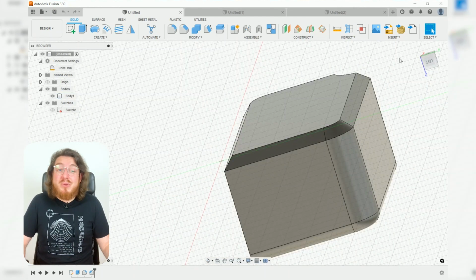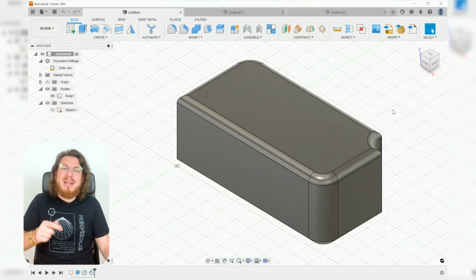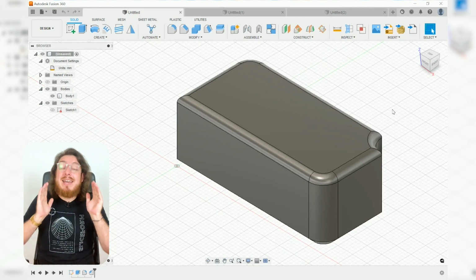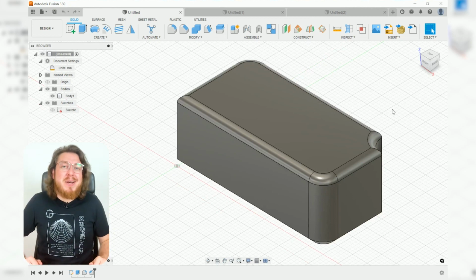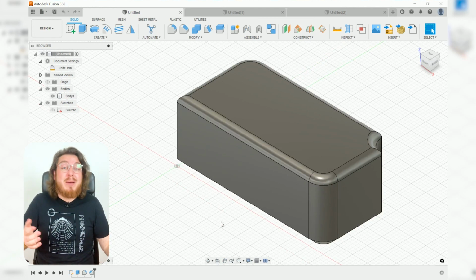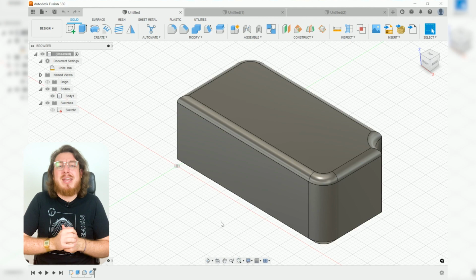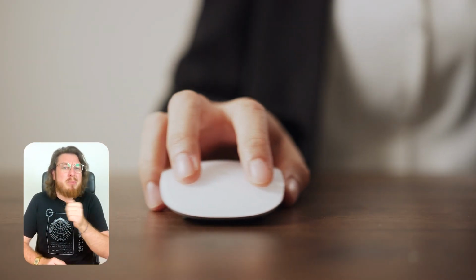Now, in the manufacturing world, anytime I'm producing an object, whether it be wood, metal, plastic, anything like that, I never want to have sharp corners. It's kind of an engineering faux pas, and you always want to remove some material, either with a fillet or a chamfer, something just to knock down the edge. It's the reason that you never see things in real life with kind of sharp corners on it.